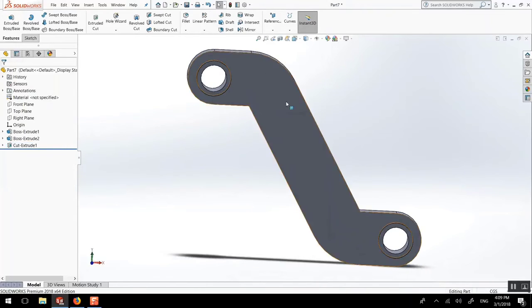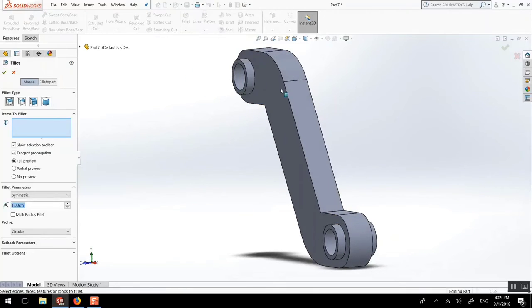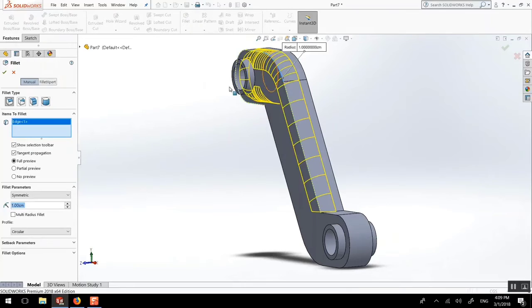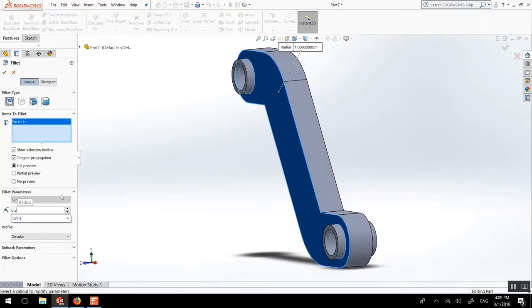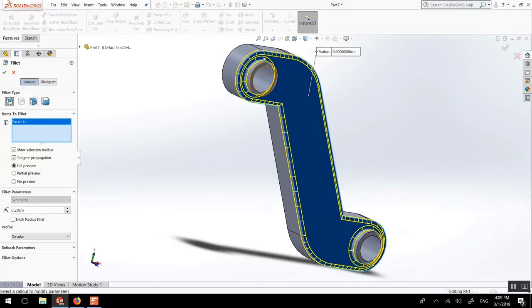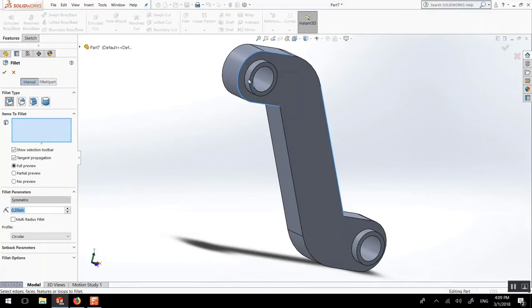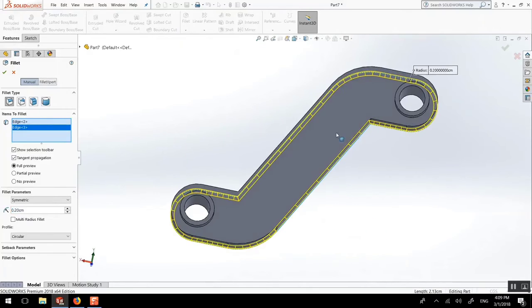If you really want to round this, usually when you do fillet, here 3D fillet feature, start by the widest one. So if you know that you're going to go very wide here, you could almost select that face and you see, drop this down. I don't know if I want fillets here, maybe. But if not, what I can do is just grab one line and it'll try its best to go all along. So always start with the wider one first.